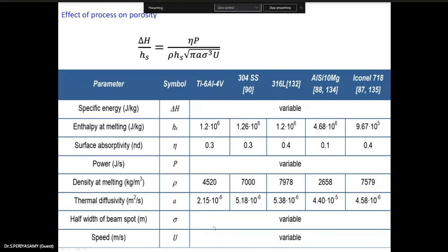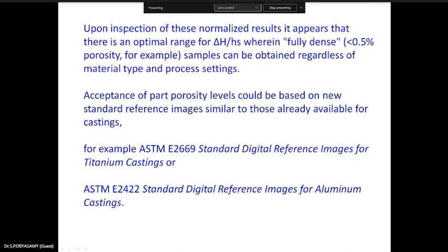The phenomenon of coalescence of particles into the melt pool can also be used to understand the influence of hatch spacing, the center to center distance between the melt pools in the build plane. So what is the hatch spacing? We have a diagram. This is the hatch spacing. Here you have one particle, and another particle is overlapping.